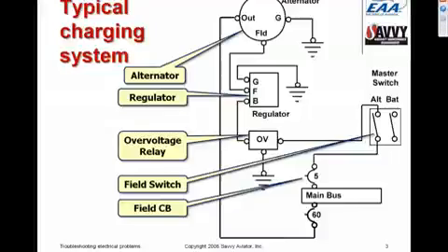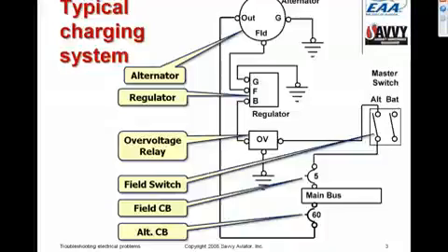Usually, it's a fairly small amperage device because typically alternators under normal circumstances will draw no more than about 2 amps of field current, and that's typically when the engine's not running, and the higher the RPM, the lower the field current that they draw. So normally this is a small amperage device. And then a high amperage breaker for the alternator output that protects the heavy alternator output wiring. So that's basically the componentry of a typical charging system.